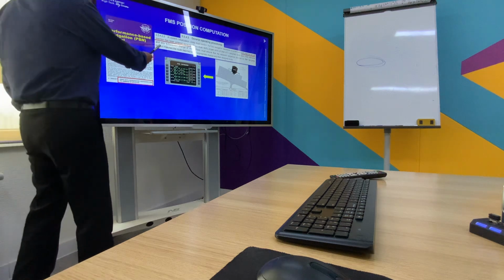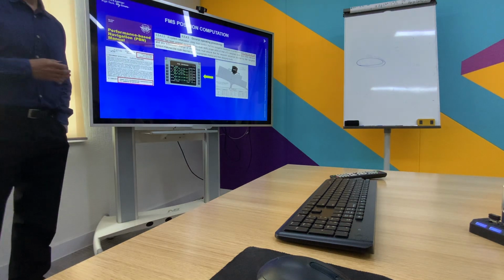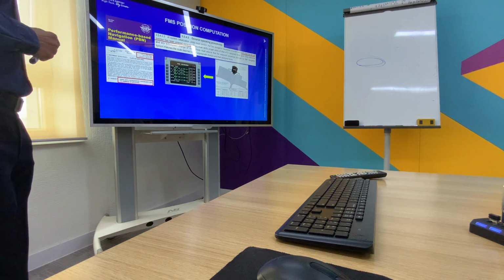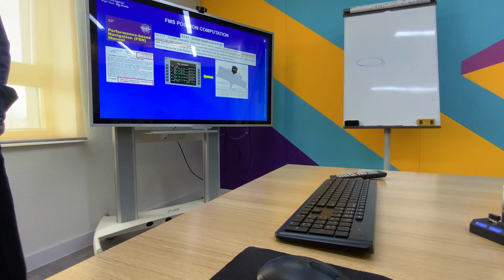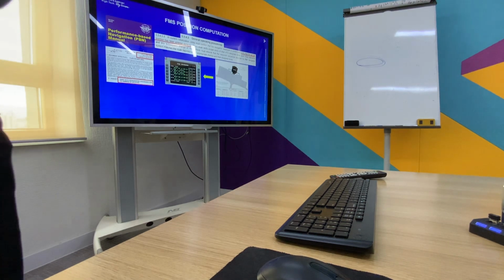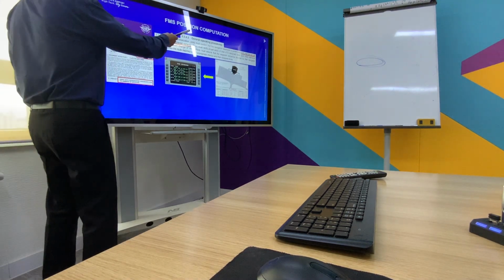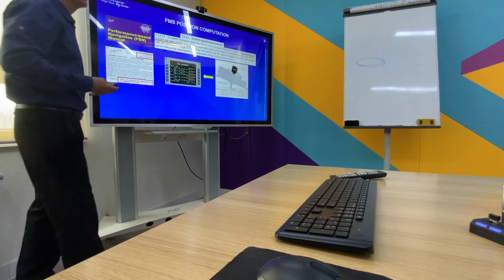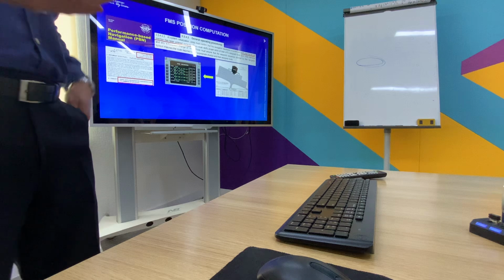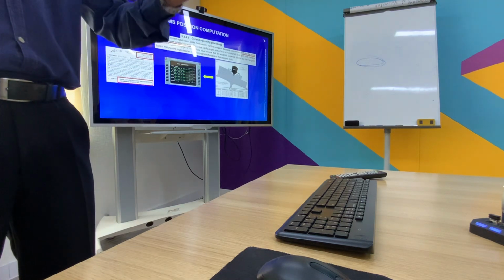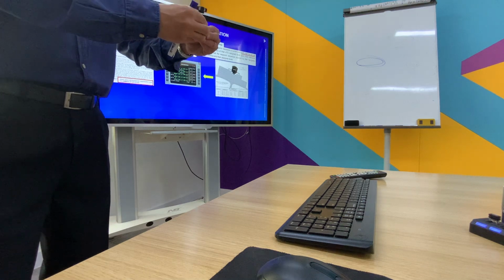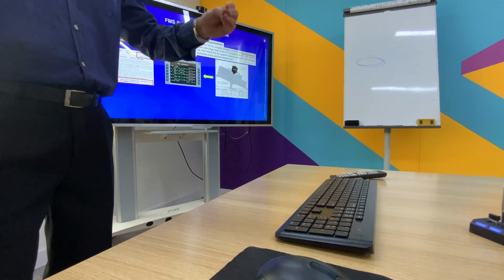And there is another statement in ICAO Doc 9613, regarding performance-based navigation. It states that we have to verify that the aircraft position was entered correctly. We know that on the E2 and the E1, the GPS will insert the position in the FMS automatically.